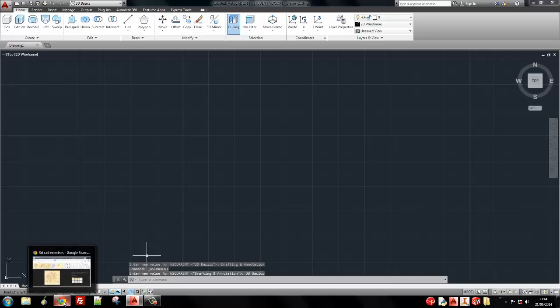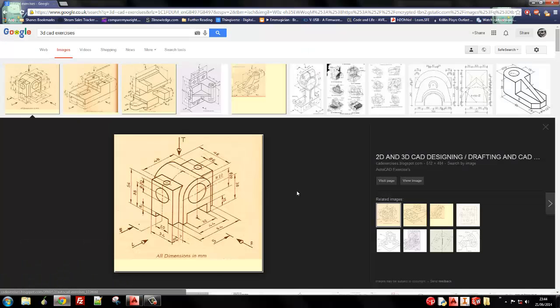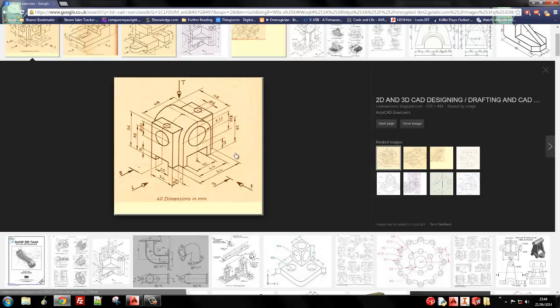Before we start building it, it's wise to get an understanding of how a shape like this is made up. So we've got the main body, which is rectangular geometry with a circle on top, which has been extruded backwards by 48mm. You've also got this other shape going through from one of the sides, from the left elevation. Technically you can build this all as one, or you can build them as two separate shapes and do what they call a union. A union bonds them together as if they were one piece, a bit like welding something to another part.